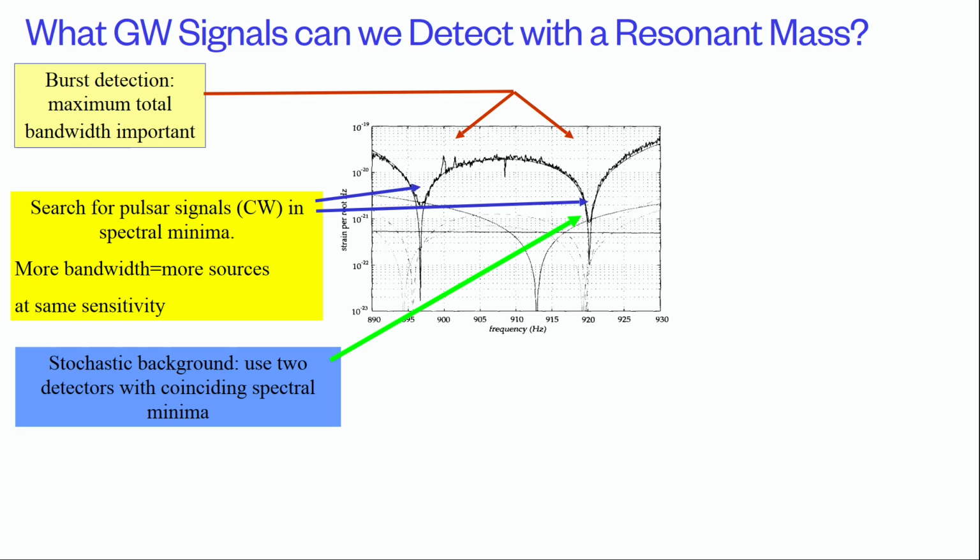Yeah. That was super useful for me, the way you phrased that. I'd like that sentence, so kind of how to read this plot. Just to follow up, if the sensitivity is given as per root hertz, it really means 1 second integration for every single frequency bin. Right. And I can assume that with time, this really scales as 1 over the square root of integration time. So it's statistically limited, and assuming my source lasts long enough, I can just rescale in that way.